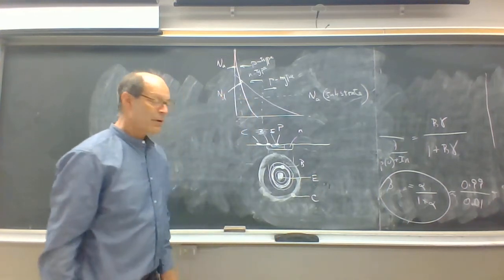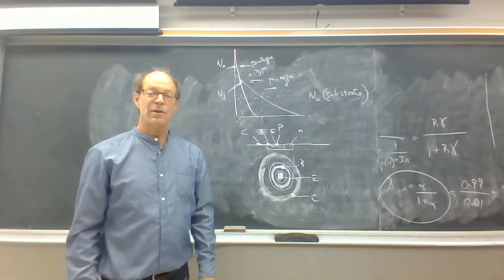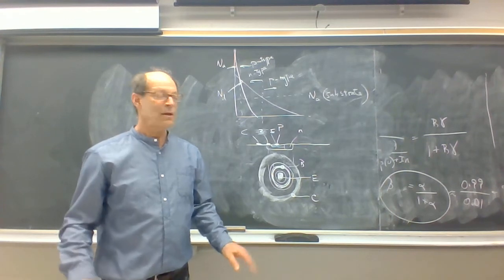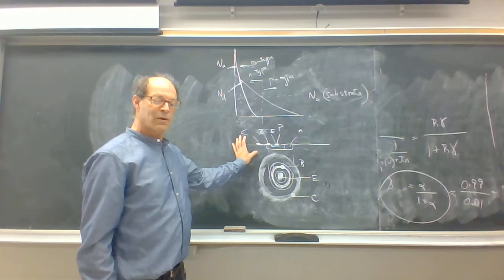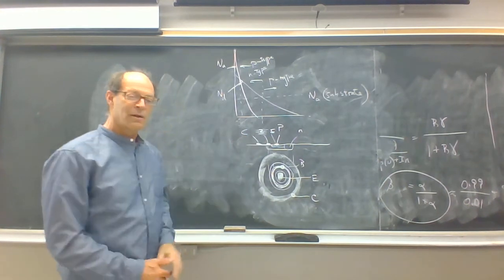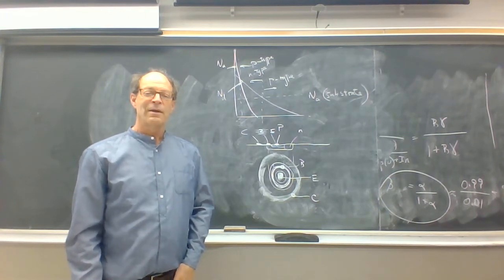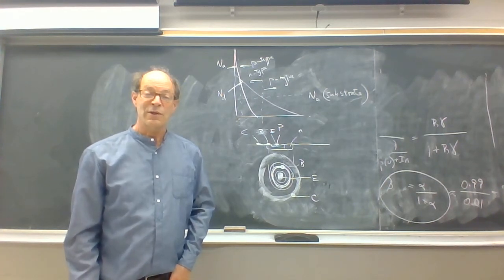So that's a very simple, very straightforward donut-style bipolar junction transistor, all planar processing, so you can create thousands and thousands of bipolar junction transistors on one smooth silicon wafer. Very cost-effective, and a revolution in electronics which occurred in the 1960s.